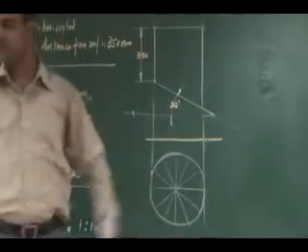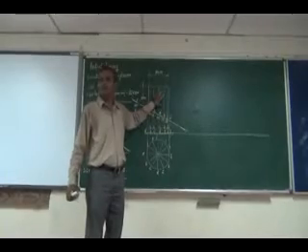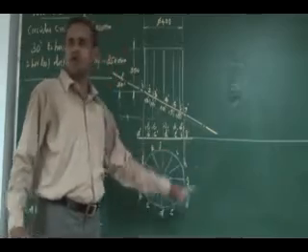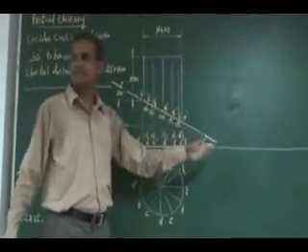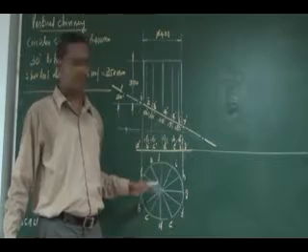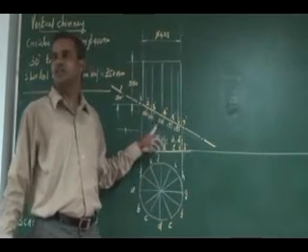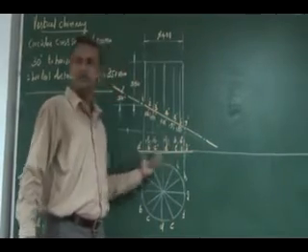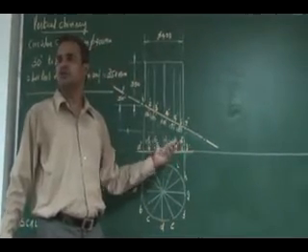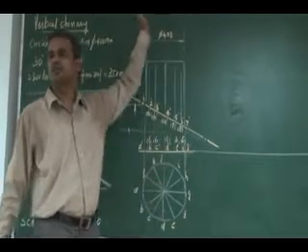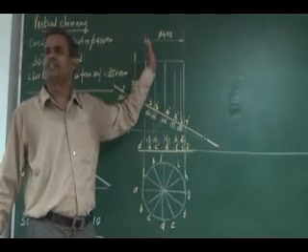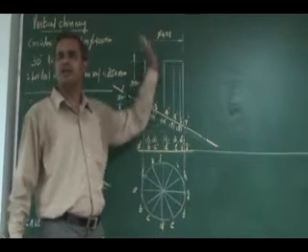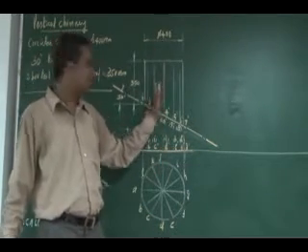First of all, finish the projection quickly. Draw the front view. The cross section is a circle, since it's a cylinder. The top view I have drawn is divided into 12 segments to mark the generator locations. These 12 segments will be projected to the front view as usual, like your solid problem. Show all the 12 generators in your front view in 2H pencil. It should not be a dark one.